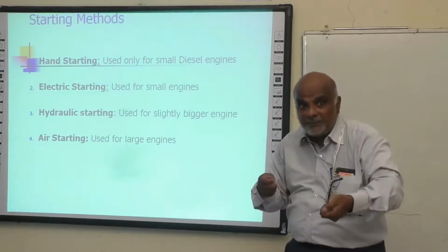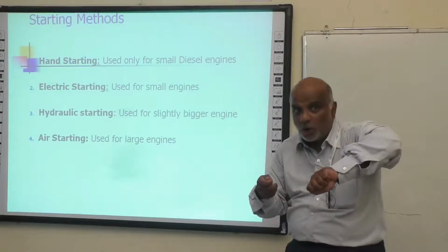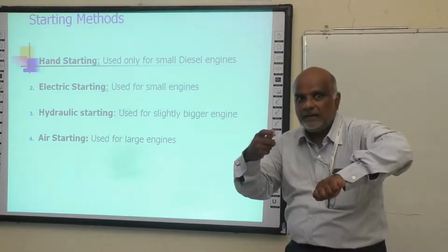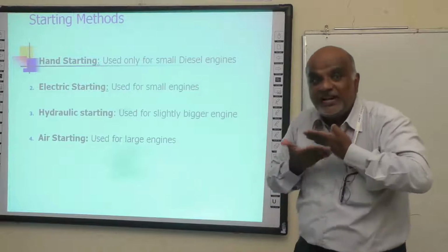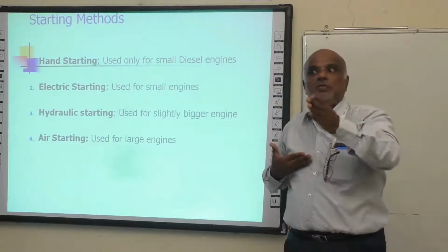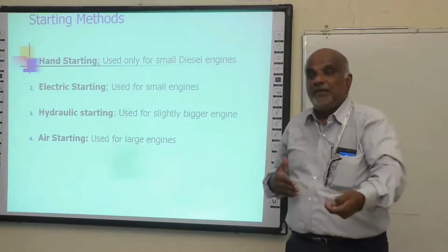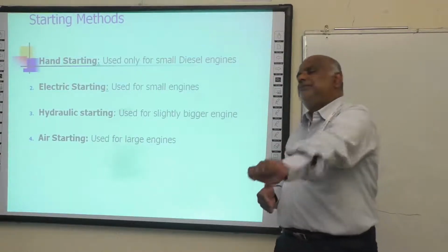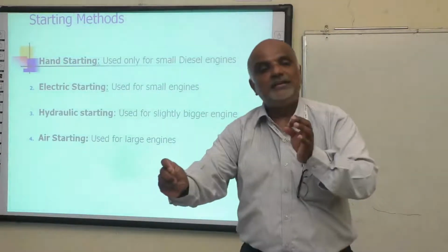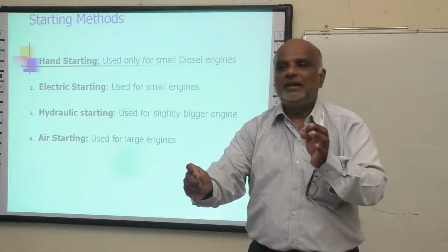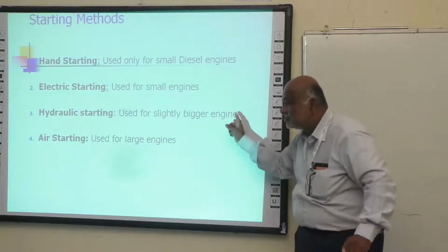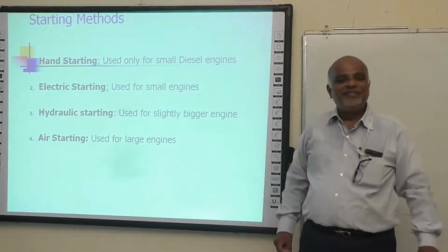That means if you open this gas more and delay your ignition, then the flame may also reach your hand or even your face. That's how many people lose their life by mistake, opening up this gas and then taking one matchstick and trying to light it. Oh no, you don't do that. Never think of that. Now, that is the place where you use the hydraulic starting system.